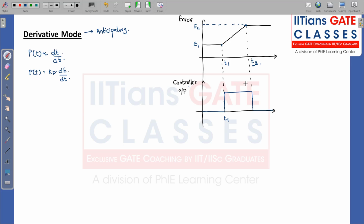You can see that at this particular time T1, my controller has already taken corrective action for the error at T2, because at T2 this is the controller output. Whatever error is at T2, the controller has already taken action for that. So that is why this is called anticipatory control. And over here my response is fast.